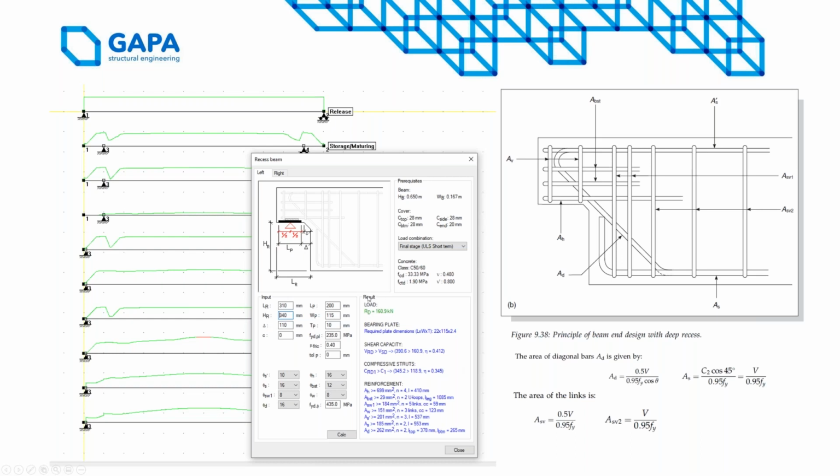On the right here, in the result area, is the shear load on the purlin, and you can see here in the reinforcement section that based on the diameter of the bar that we input, that we pre-select, the program tells us the total required area, and then it determines the number of elements, whether it's longitudinal bars or links, and spacing and recommended spacing of these links.